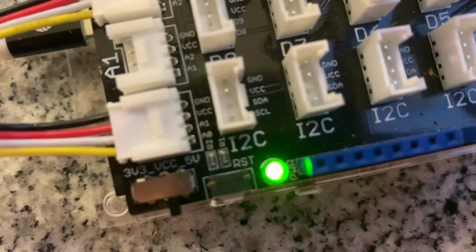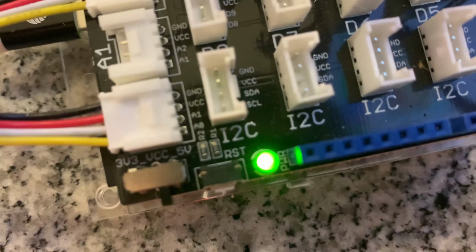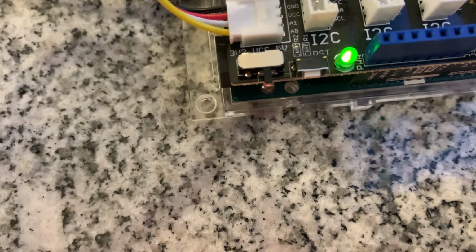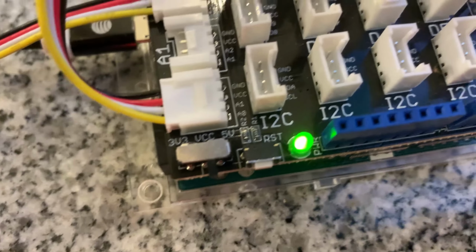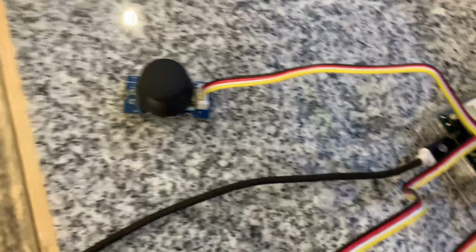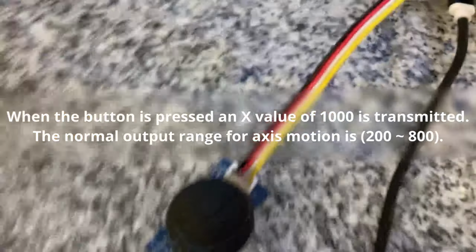So if we look over here at the base shield, we can see here we have ground is our black wire, red is our power, A1 is translated to our Y value, and then the yellow wire becomes our X value. And then when we push the button down, that transmits a really large signal to the X value so that we know the button's been pressed.